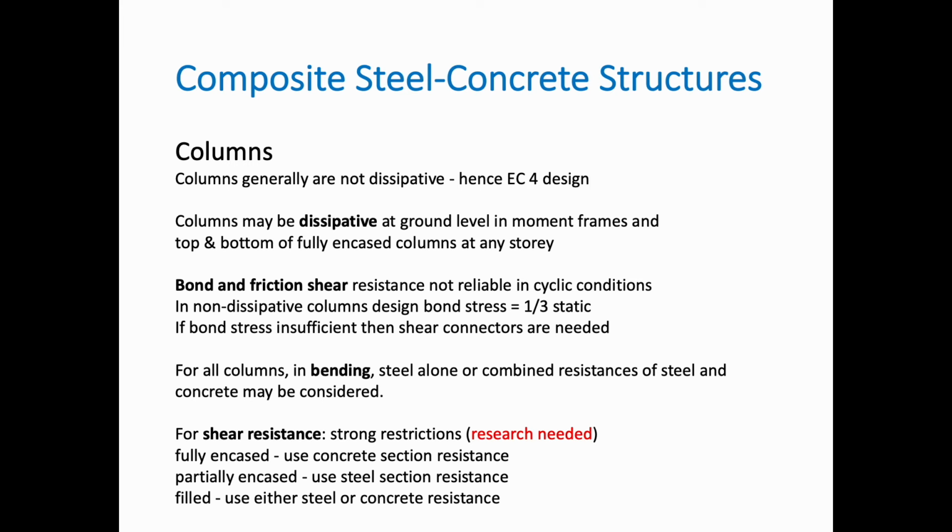In most cases, for long columns, and especially if we use them in significant applications, shear connectors will be provided. We do not overdo it because there are issues with the concrete compaction, and of course it increases the fabrication cost a lot.